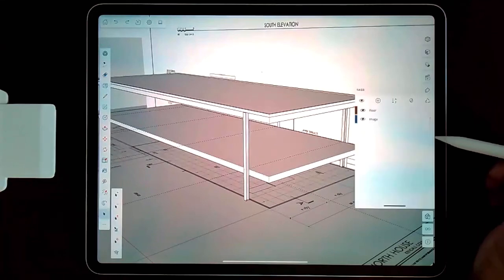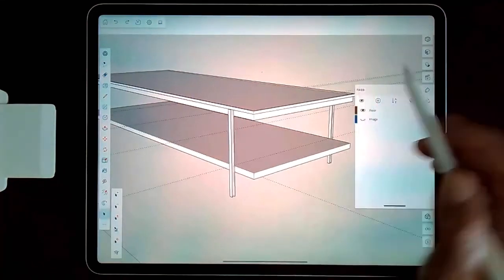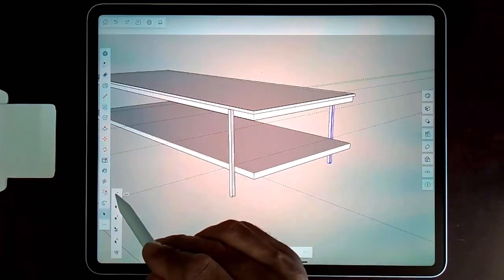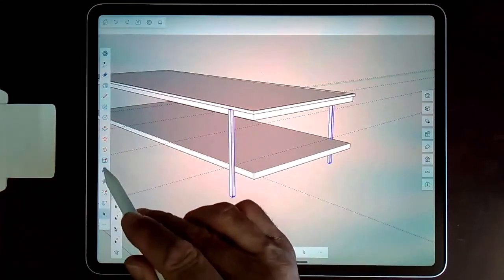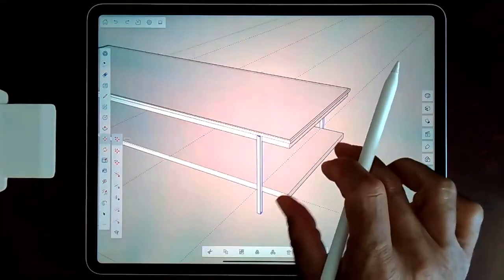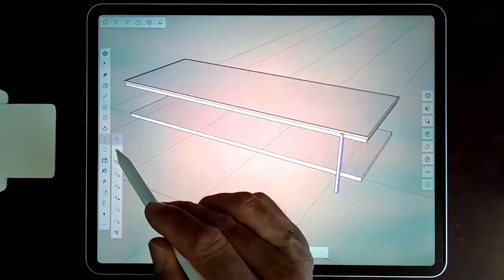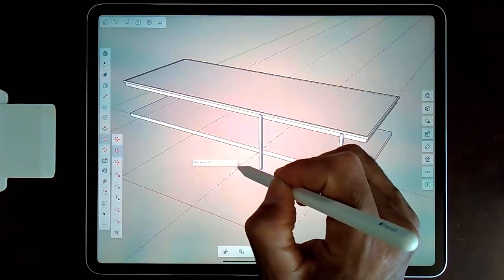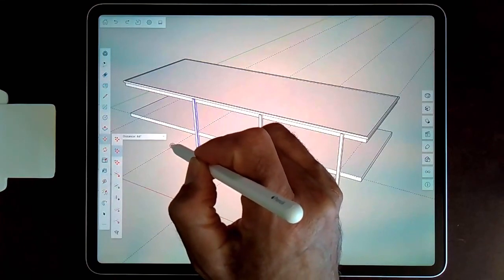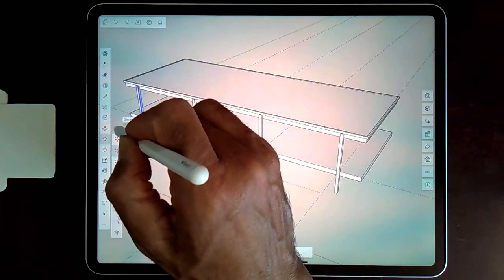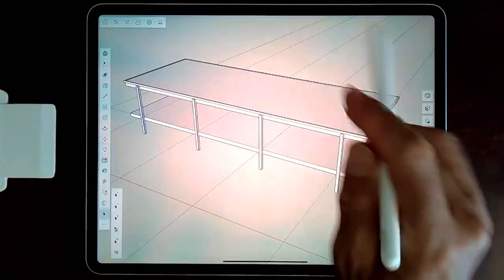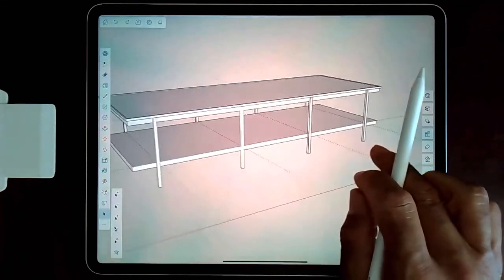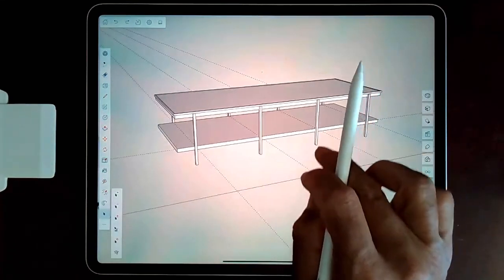And so now we can perhaps hide our drawings from view and just select those two columns. We'll do the add modifier on the selection and use the move tool in copy mode and actually in stamp mode, and be able to just follow along the red axis and just stamp these columns along the way. And so with that, we have the main structure of the building started.